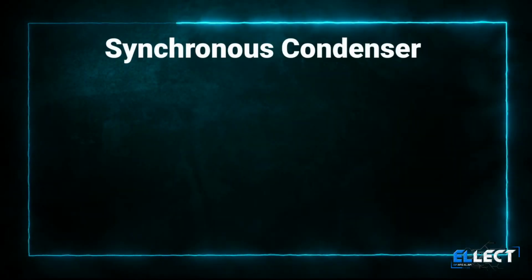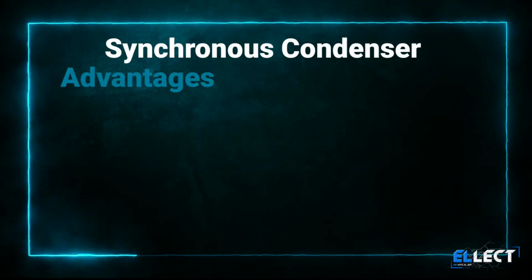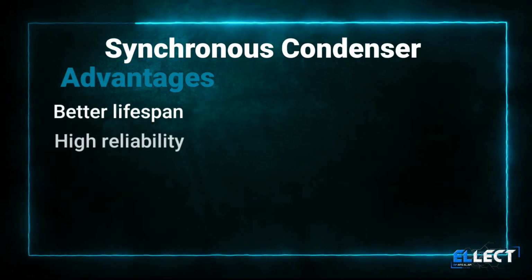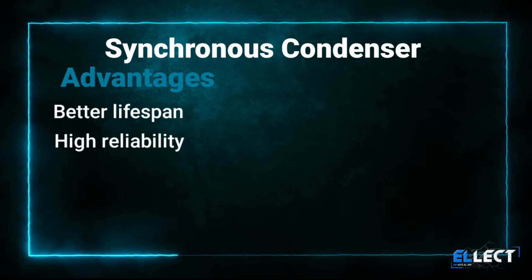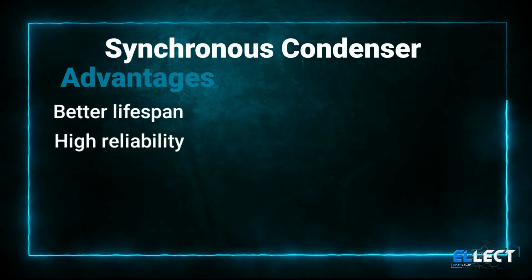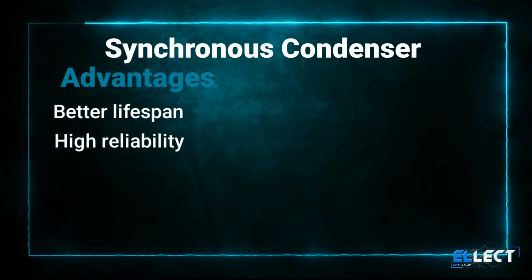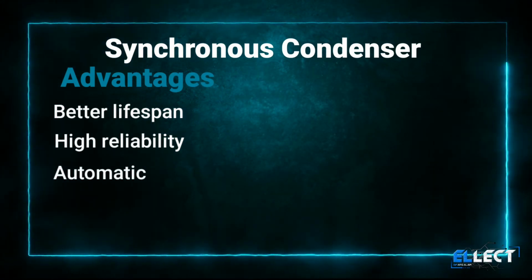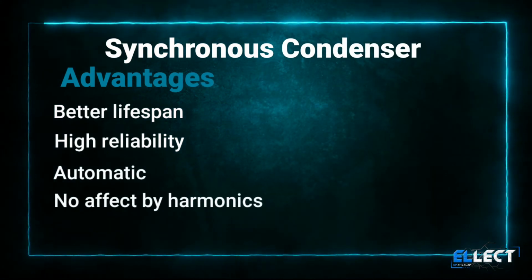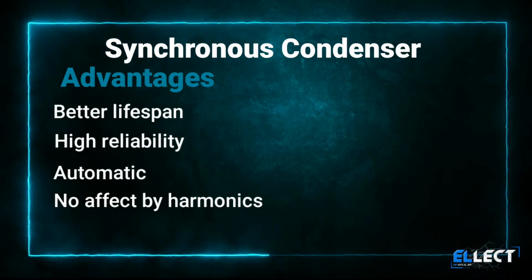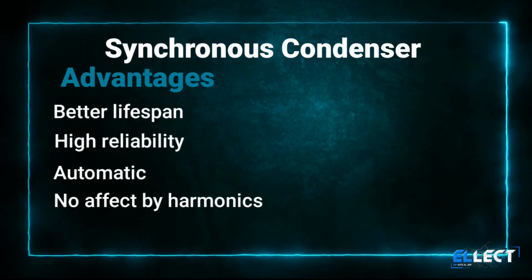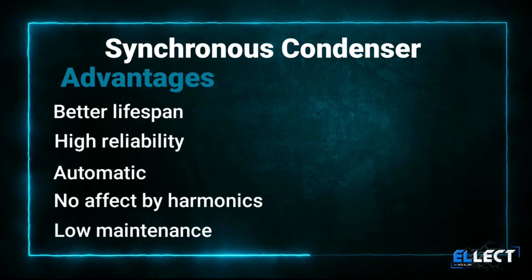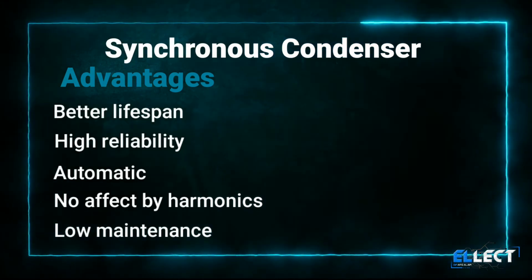The very first advantage of the synchronous motor is its high life, almost 25 years. High reliability is here. Stepless adjustment of power factor. It means no steps are required to adjust the power factor. It is not affected by harmonics. There is no effect of harmonics on it. No generation of harmonics here. It requires low maintenance. The only maintenance is bearing and greasing.